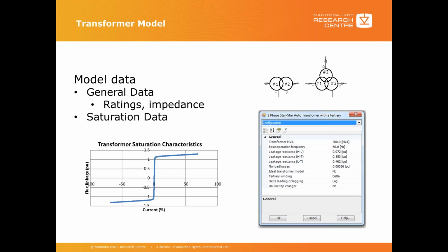Transformer model. You can use the general data, like rating and impedance, and also you need the saturation data for the transformer. These data can be obtained from manufacturer data sheets.